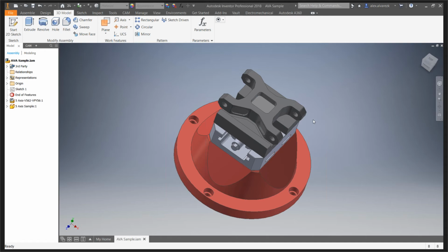All right, perfect. Before we get started though, for those of you that don't know, HSM stands for high-speed machining. So along with HSM, you get all the advanced toolpaths that come with it, one of them being adaptive clearing. You may have heard of adaptive clearing here and there, but that's really the industry-leading high-speed machining strategy, that reduces your mill time and extends the tool life. And we'll jump into a little bit of how that toolpath is able to do that.